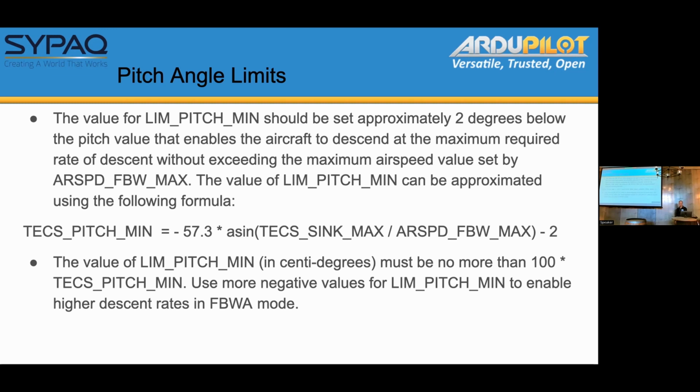We set pitch angle limits, and by the way, if you've got questions because of what I'm doing here, probably appropriate just for people to stick up their hand and say, yes. Where is the 2 degrees coming from? Like, the 57.3. So the 2 degrees, like why 2 degrees? Why? Because you have a little bit of turbulence. That's just due to turbulence, gust response of the aircraft. And there can be some fluctuations around that. Right, but why 2 degrees? Why not 3 or 4 or, you know, 1? I said rule of thumb. 2, I found 2 to be adequate for most applications.